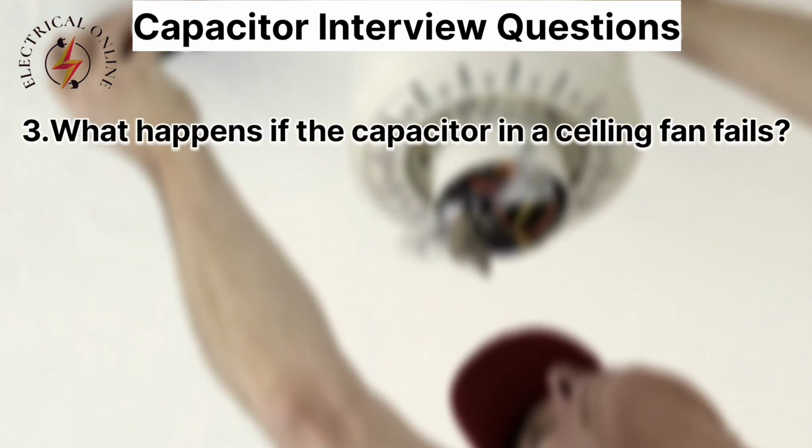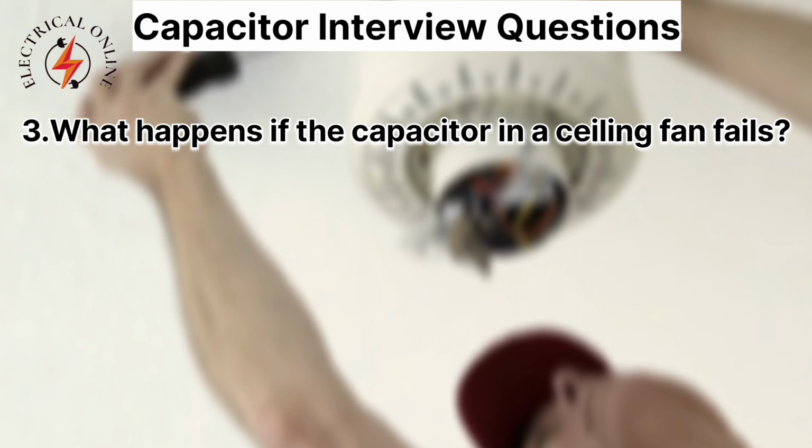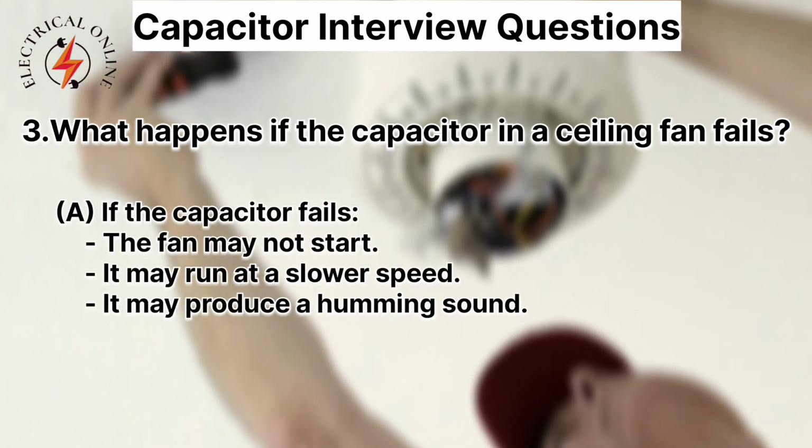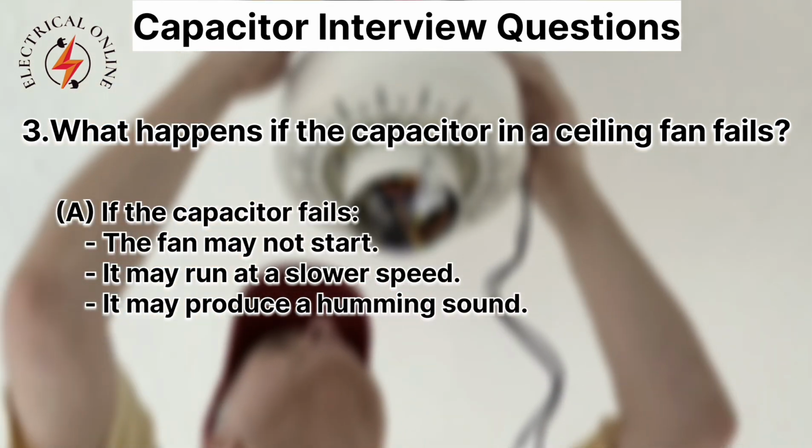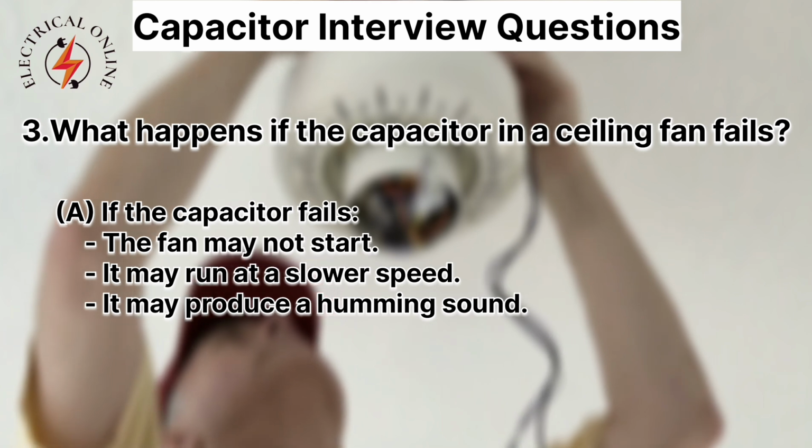3. What happens if the capacitor in a ceiling fan fails? If the capacitor fails, the fan may not start. It may run at a slower speed. It may produce a humming sound.